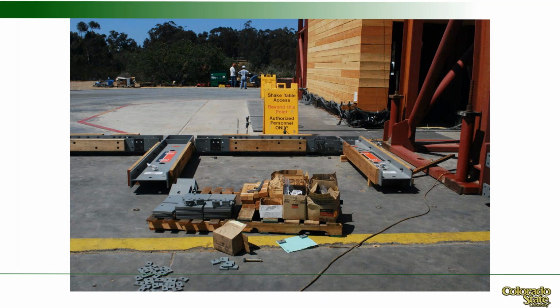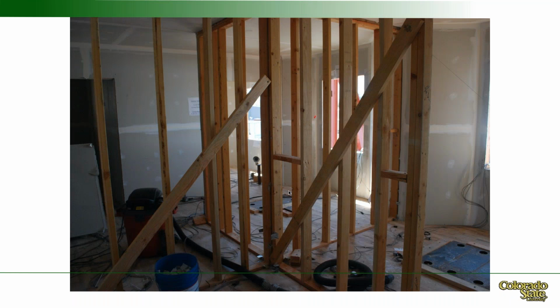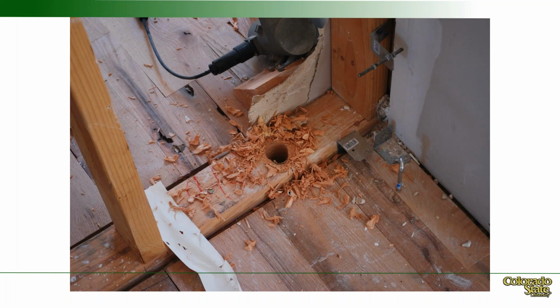And so this is the steel special moment frame being pre-assembled to bring into the building. This is the second story, and this is two intersecting walls. They were just walls. They're going to become intersecting shear walls shortly. This is installation of the continuous rod hold downs to control uplift. And that was part of the design as well.